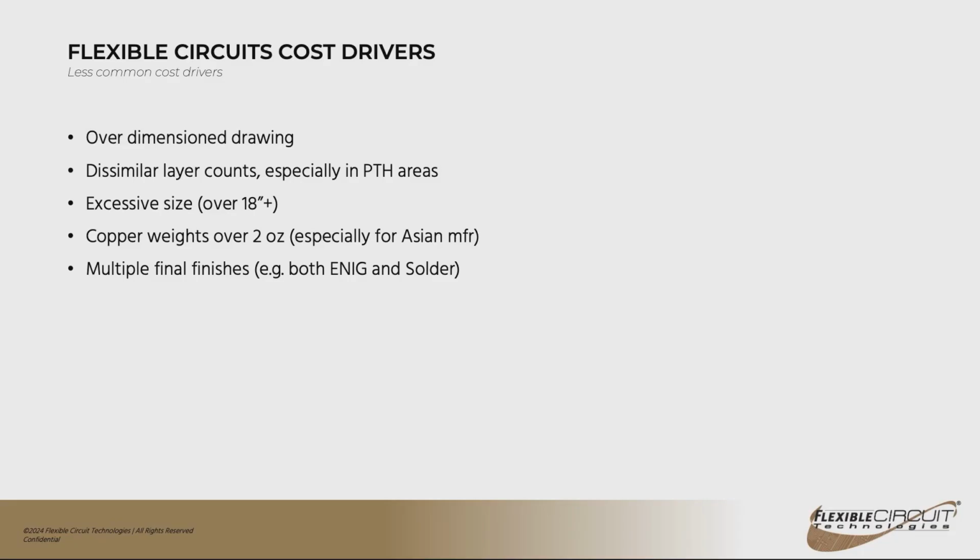What is the smallest bend radius that the flex can bend to? Mark? Yeah, that's a very good question. The smallest bend radius is typically driven by the circuit type and the circuit thickness. The thicker the circuit is, the greater that bend radius has to be. And so what we typically do is we calculate a bend ratio, which is the ratio of the circuit thickness to